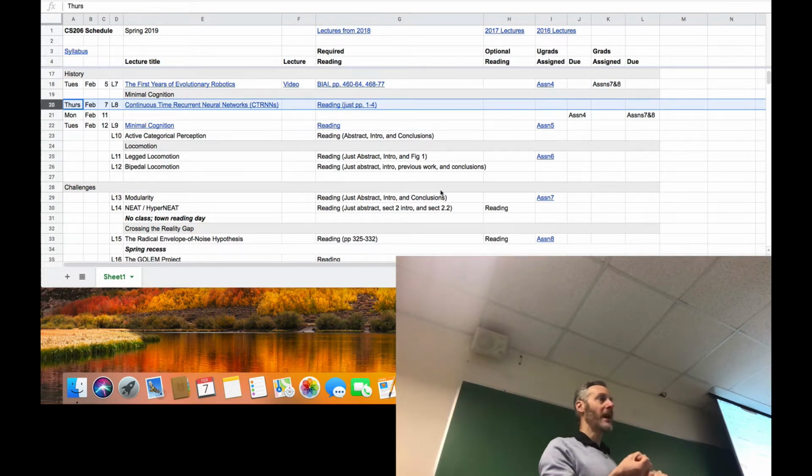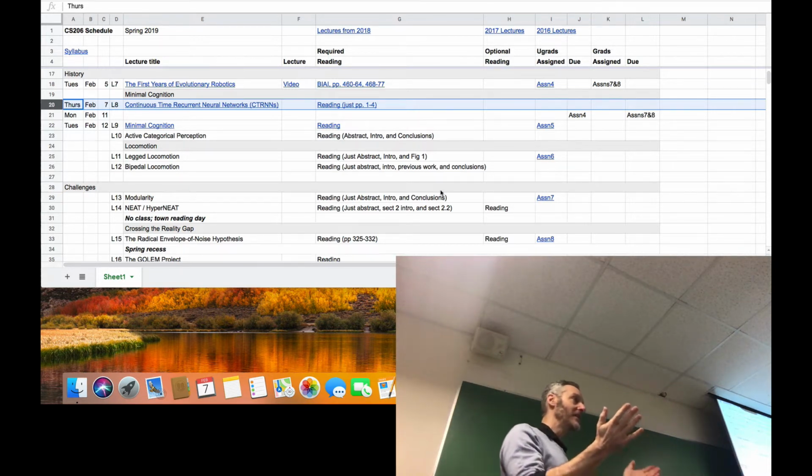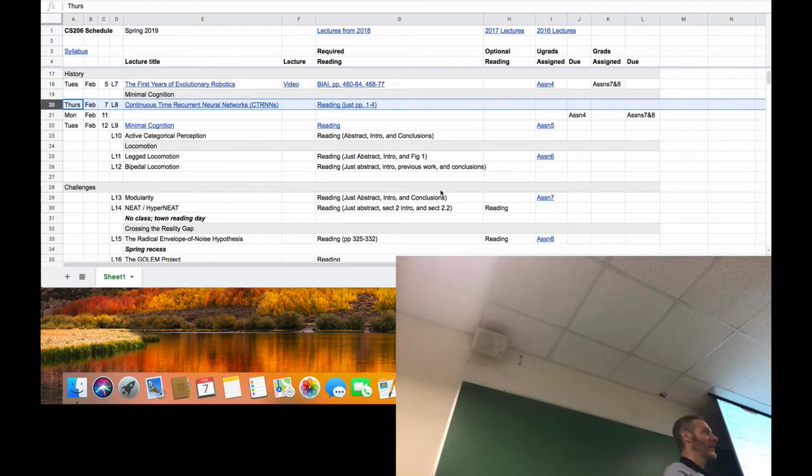The other thing we saw in the Kepler experiment was that evolution exploits various aspects of the opportunities and limitations of the machine itself. So the Kepler drove at max about 48 millimeters per second, which was evolution fine-tuning how fast it could get the robot to move given the refresh rate of the sensors, even though the top speed of the robot was faster. We'll finish today by discussing this strange gantry robot we saw that was created at the University of Sussex in the UK at about the same time as the Kepler experiments.